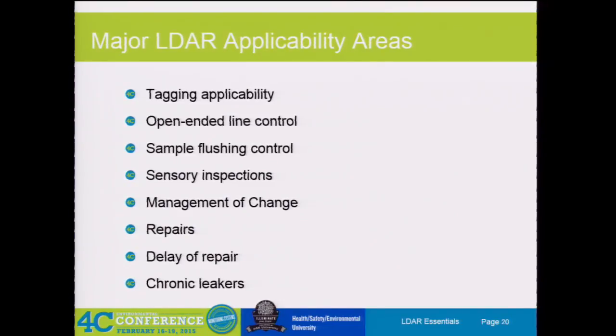How many people have had their MOC program not get everything that's in the field? Okay, so we all have these, but we also have midnight valve installation. That guy that walks out and all of a sudden I got this brand new shiny valve added on that should be in the LDAR program. Yeah, so we all know that there's gaps.